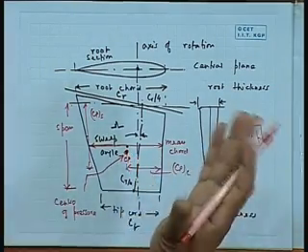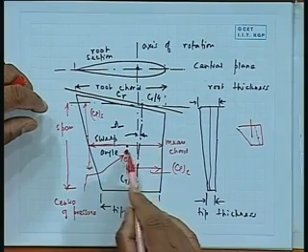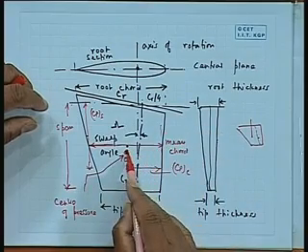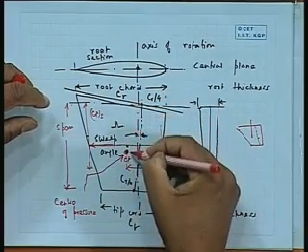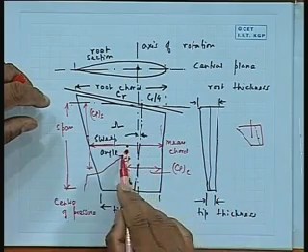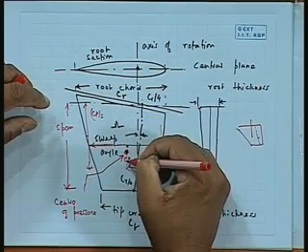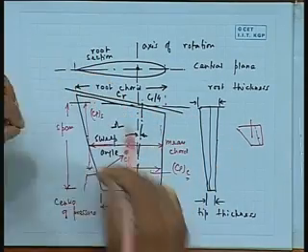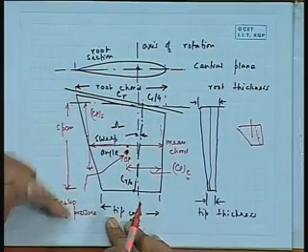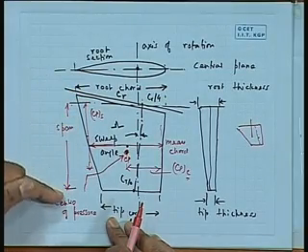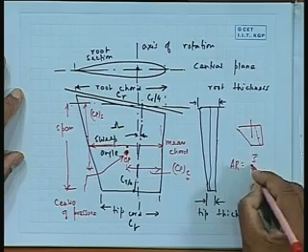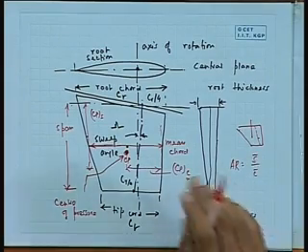For any point, location is given by x and y coordinates. So here the coordinates are measured as how much it is from its mean line, how much it is from one edge, and how much it is down from the top. You can call this length CPC, the chord length, and you can call this CPS, that is the length along the span. This side is the chord, this is known as the span. And there is obviously aspect ratio, span by chord, mean span by mean chord.